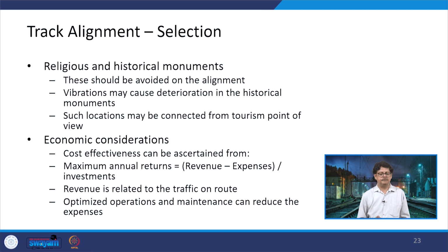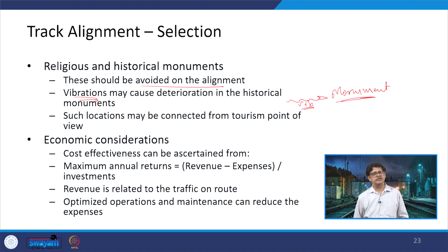Religious and historical monuments, in this case as far as possible we should not pass through them. One of the reasons is the vibrations, and these vibrations which pass through the land to any monument may be detrimental to it because of the structure which is very old, and these vibrations which are coming may cause a deterioration here. So, as far as possible we should not consider them, but we can consider them from the tourist point of view. In that case, some bypass mechanism has to be taken care of.